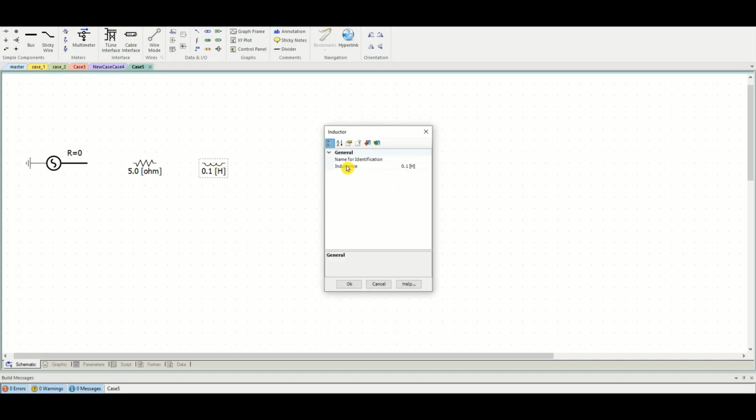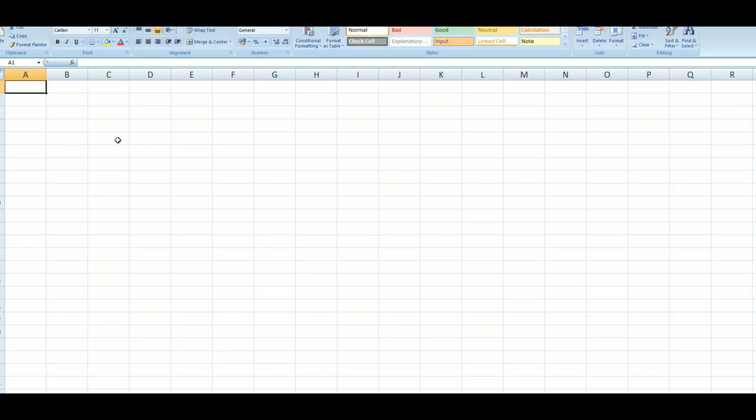And for this inductance, what will be the value of this inductance? We need to calculate. Let's say the grid X by R ratio is 20. It is given. So this input is available and R is 5 ohm.